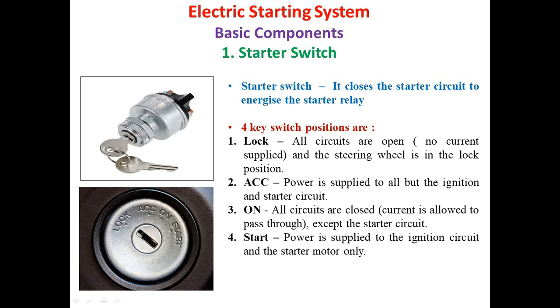Here the starter switch which is utilized is spring loaded. So once the engine is started, it again comes to the on position. When it comes to the on position, the starting circuit again gets open because now the engine has started running on fuel energy because of the ignition system circuit. Also, once the key comes to the on position, all other accessories again start functioning. So this is how the 4 positions of the starter switch work.